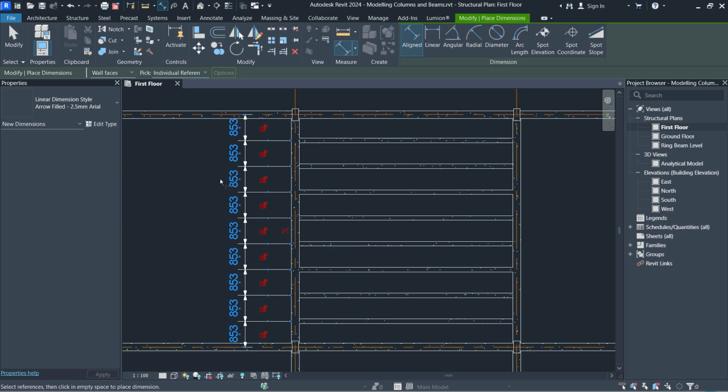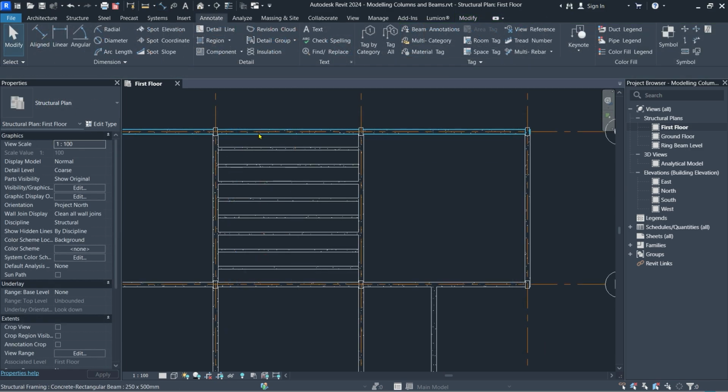You can see the spacing. I want to illustrate what ribbed slabs mean. It's basically smaller beams, for example, spanning in this direction, but having a thinner slab. Now, instead of having a slab of 200, for example, I can have one of 50 millimeter seated on these smaller beams.